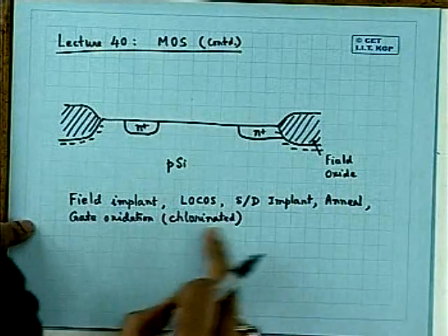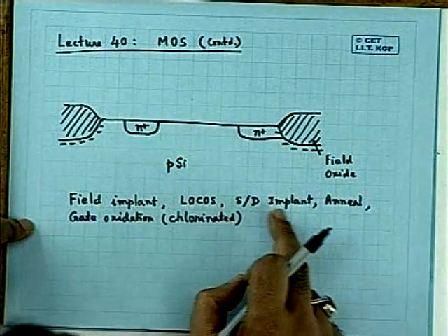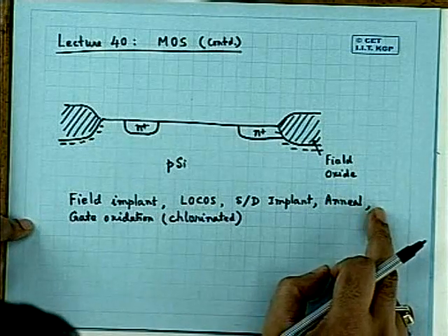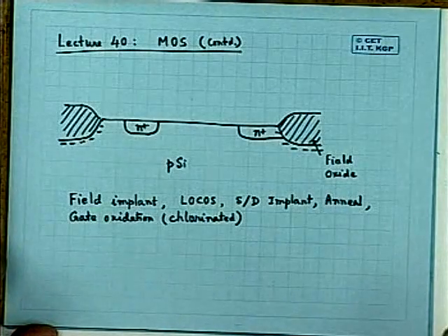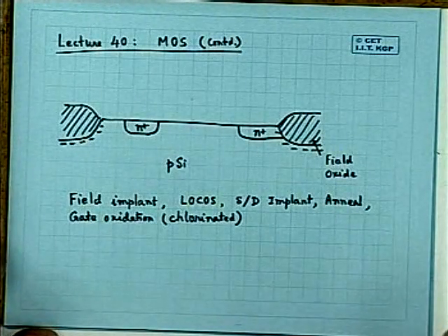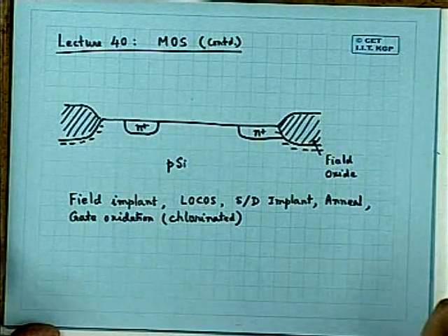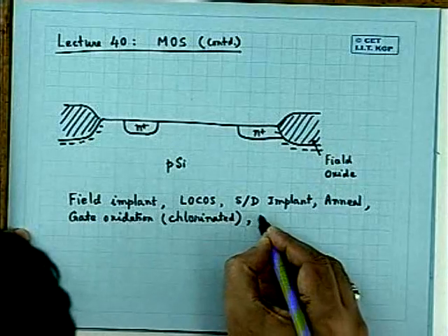So this next process, next to source drain ion implant and anneal, you grow the gate oxide, which is ultra thin in modern MOSFETs. Thickness may vary from about 100 angstrom to about 300 angstrom, depending on the technology. Even below 100 angstrom oxide thickness is also being used today in research scale, in R&Ds. Okay? Thereafter, you deposit a polysilicon film. Next is polysilicon.